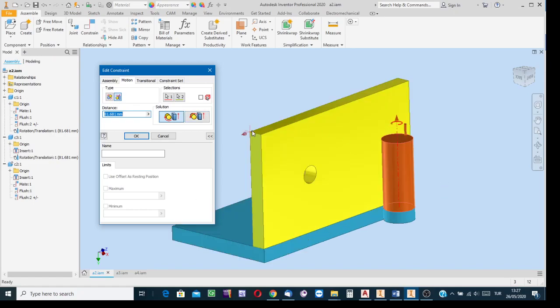From the simulation, you see I have an arrow, but a banded arrow as well. And the longitudinal axis of the brown one has been highlighted. And in the dialog box, I see not the assembly tab, but the motion tab has been selected. If one surface is cylindrical and the other surface is flat, then select this type. If both of the surfaces were cylindrical, then I would select this type. For instance, there are two spur gears, and one of them is to rotate the other. Both of them have cylindrical rims, so select this type and then input the constraint. But in our case, the surface of the yellow one is flat, so select this type option.